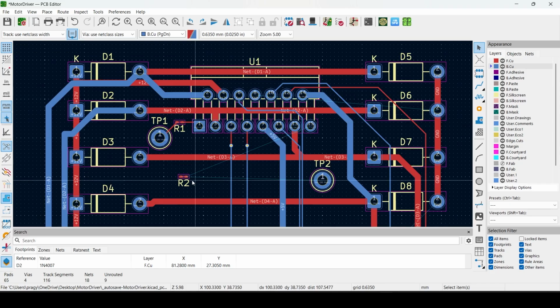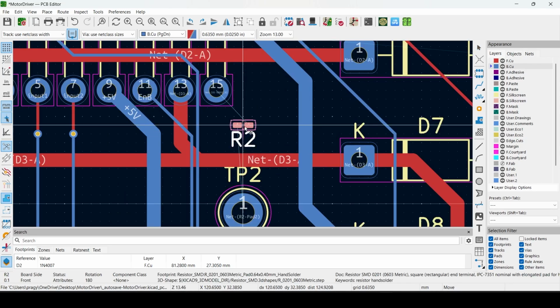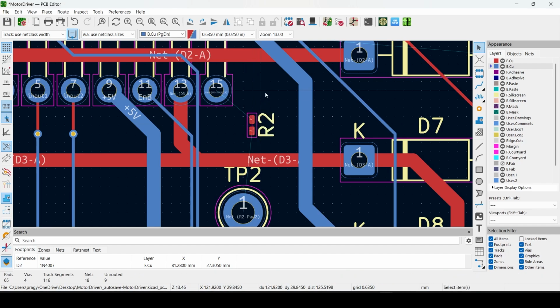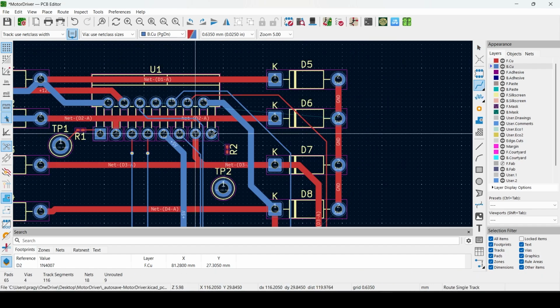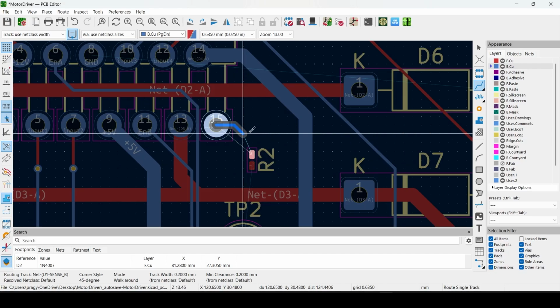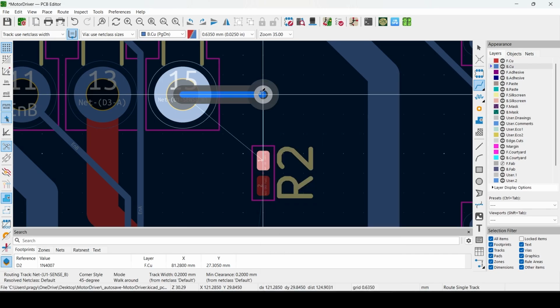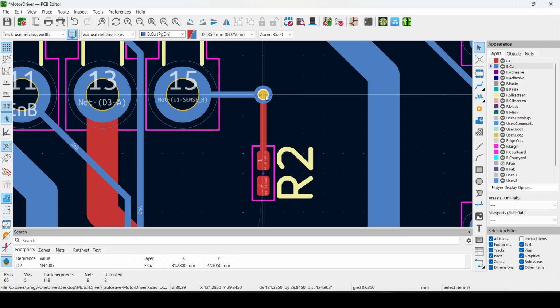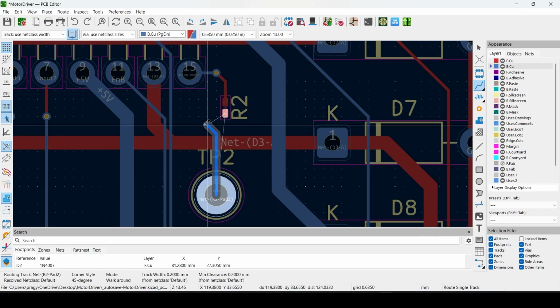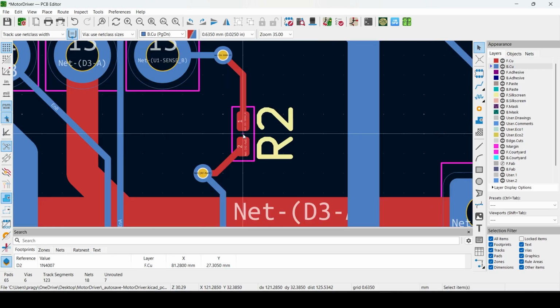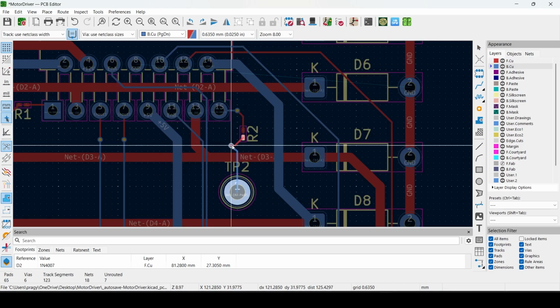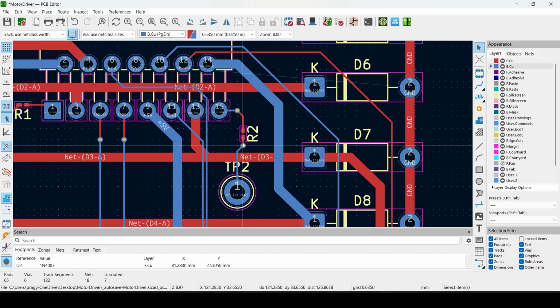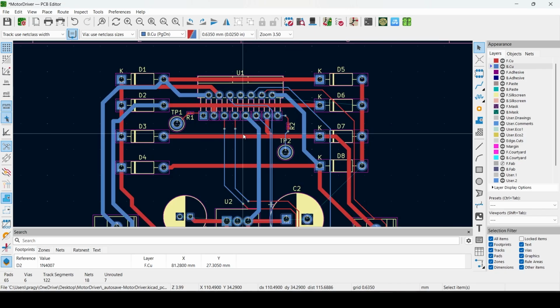I thought it was here, but that's okay. We can just quickly move it, rotate it, place it somewhere here, and quickly connect it, place two vias and connect it, remove the right angle. Now I'll place two vias, connect it, quickly fix this one as well. So I think we've connected all the signal and the power pins except for the grounds, of course.